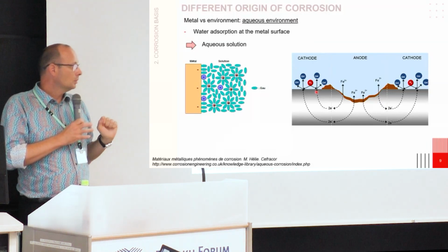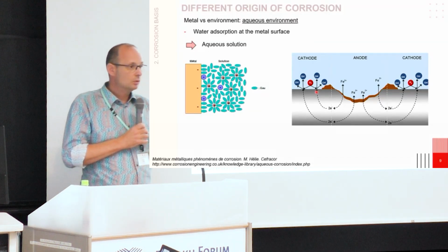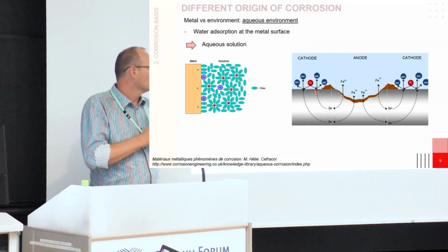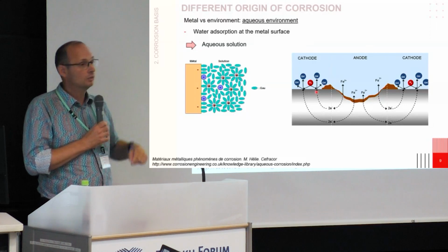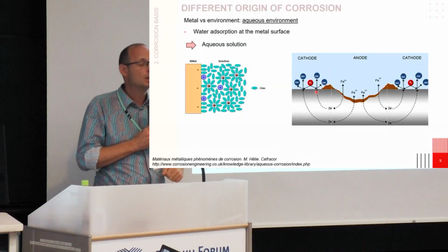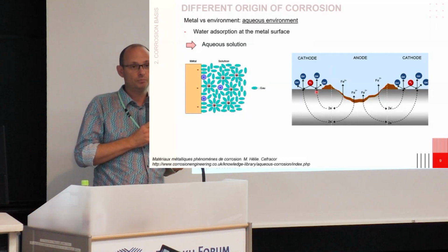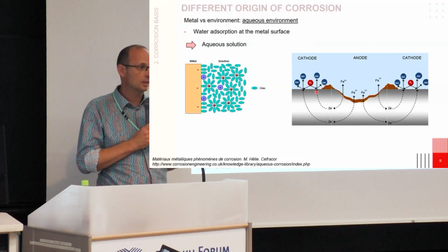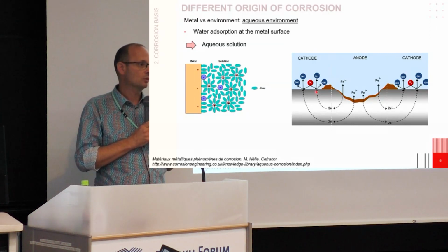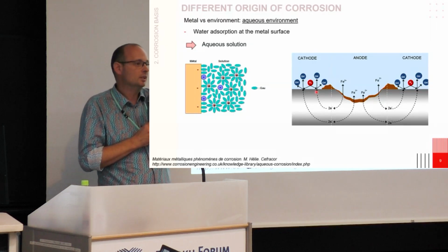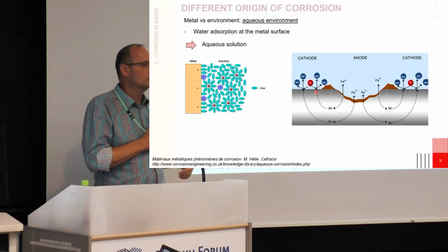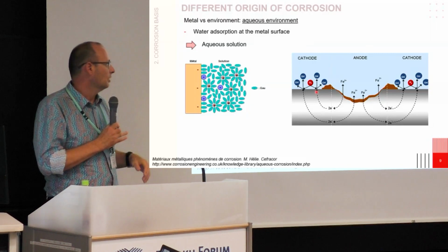Now, corrosion in water will occur because of electrons. I already said that a lot. And for that, we need to have two reactions at the same time: the first reaction that will release electrons, and a second reaction that will keep or attract electrons. If you touch a steel rod in water, it doesn't give any electricity; the electrons are already exchanged and stable.